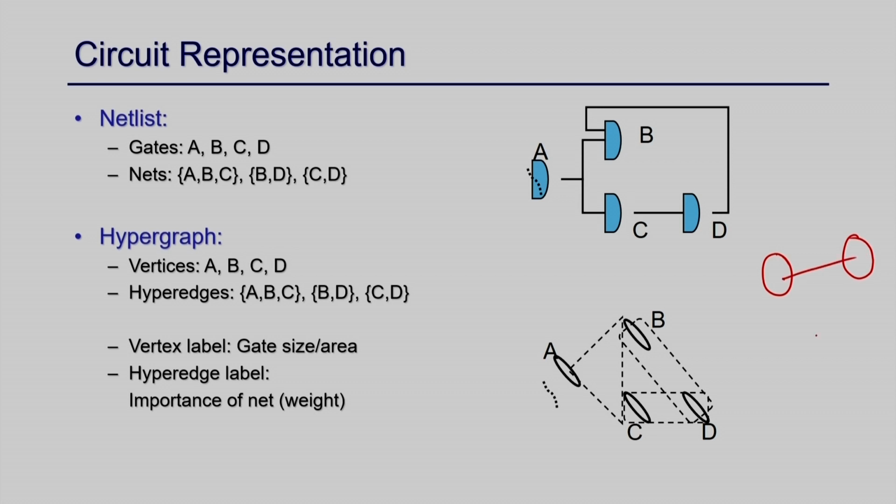So far we have discussed that, but whenever you have multi fan out, this AND gate output is going here and here. So, then how do you represent this node? This is something called hyper edges. There is one source and multiple outputs. So, this kind of edge is called a hyper edge, where you have to represent the edges between a set of nodes, where the first start node is the source and the rest are the destinations. So, here A, B, C means A is the source node and B and C are the destinations. This is how we can represent the hyper edges.